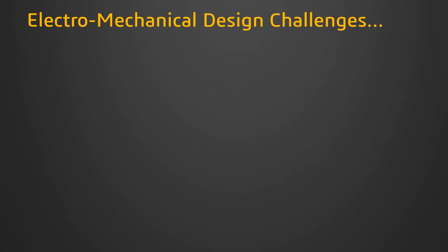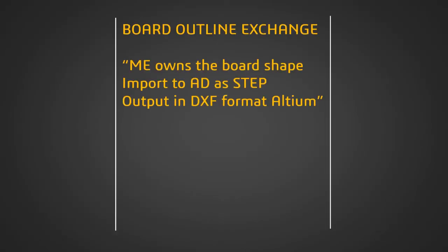What are the challenges for the electromechanical design portion? The outlines are typically owned by the mechanical engineering team. Oftentimes you're exporting DXF files and STEP files, sending them through email, importing them into your PCB tool, redoing a drawing, or doing additional investigation into what's really going on with the information that was provided.